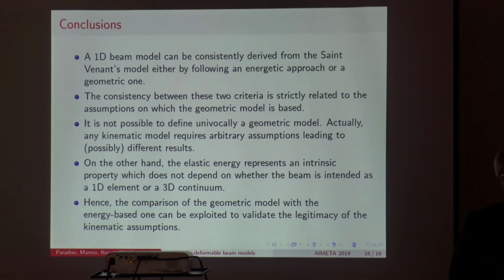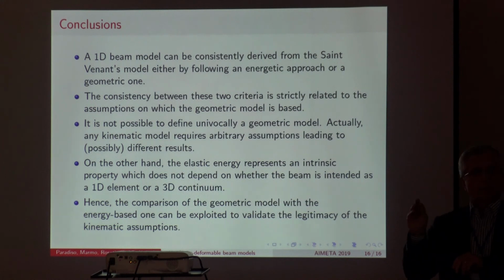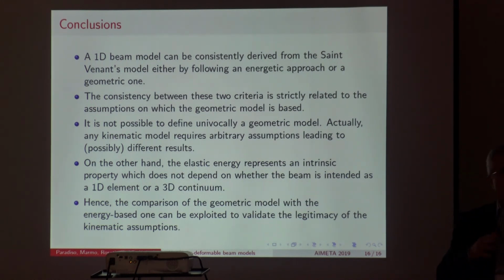Not completely. In my personal theoretical framework, which I of course try to teach to the students, you have two different problems: bending, with a special point, the center of gravity; and shear, with another special point, the center of twist. In my opinion this is much clearer.